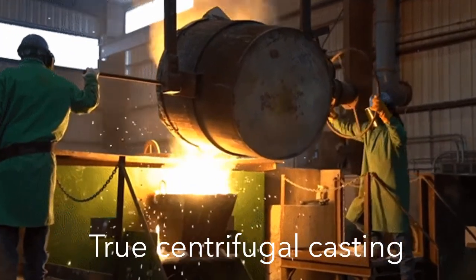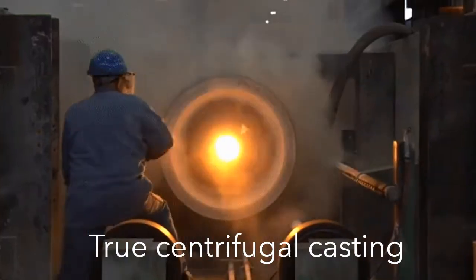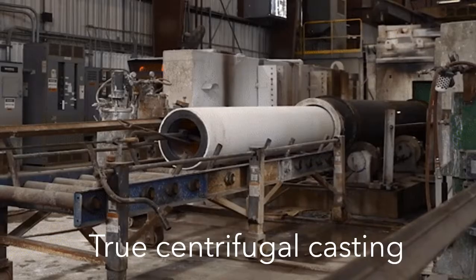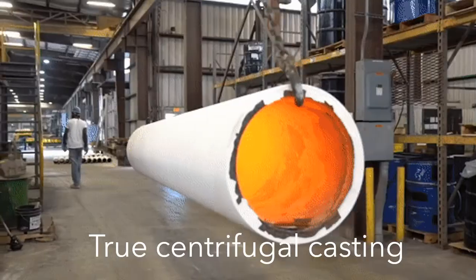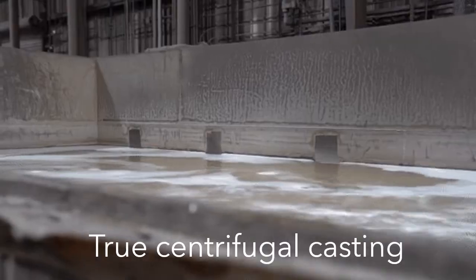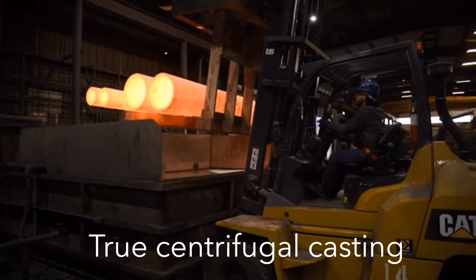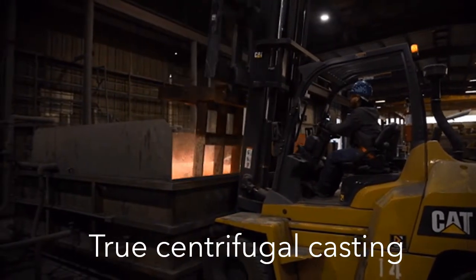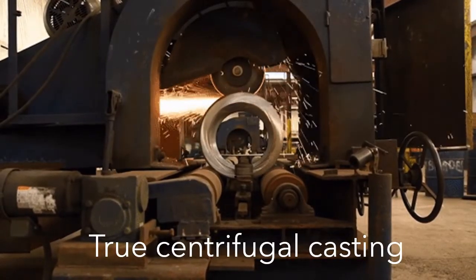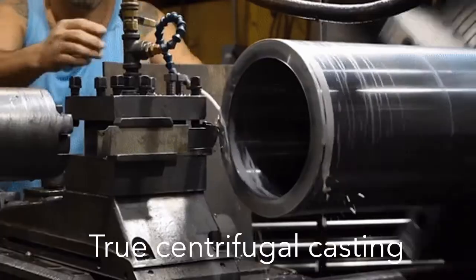The outside shape of the casting can be round, octagonal, hexagonal, or any other shape, but the inside shape is theoretically perfectly round due to the radially symmetrical force. The continuous solidification starting from the outside surface due to the chilling effect of the metal mold eliminates shrinkage and inclusions from the casting. The centrifugal force makes cylindrical shapes with accurate concentricity. No traction and no stress-inducing factors during solidification keep the residual stresses to a minimum.